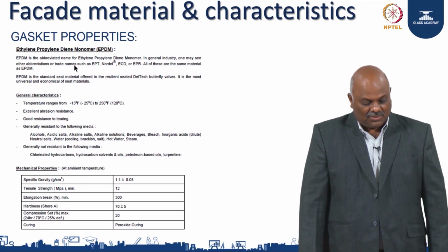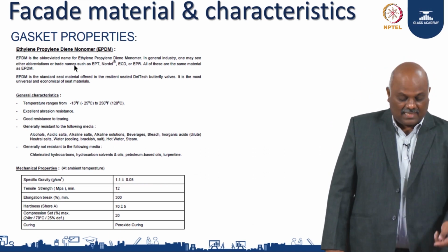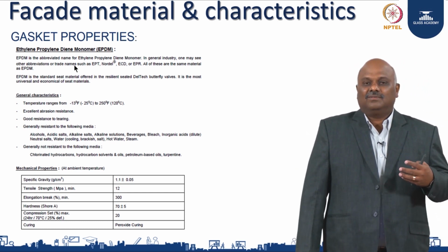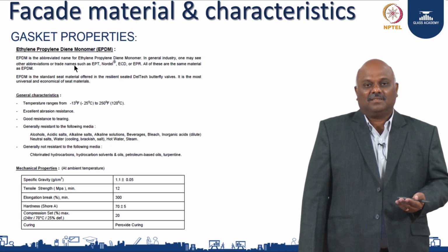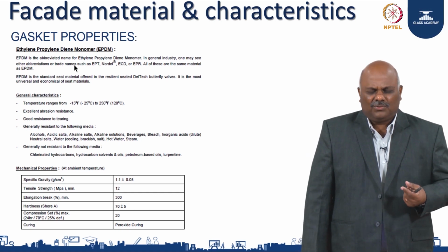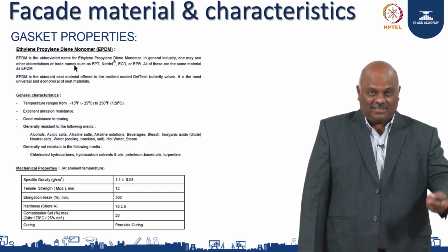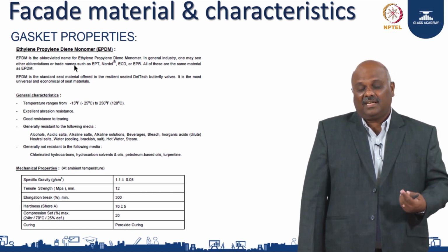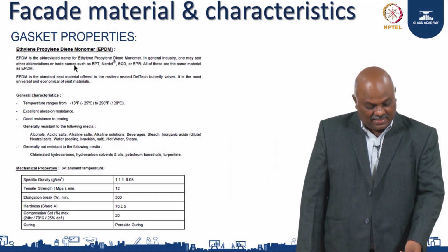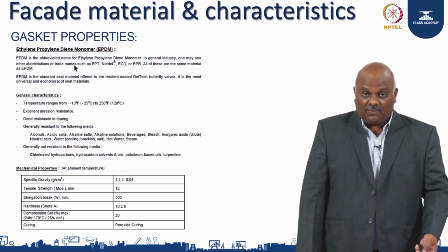So, these are the properties. If you run through, you will see EPDM, and again the choice of gasket and its hardness depends on your requirement. It is not something you just get off the shelf and put up. So, you design it, you understand what strength I need, whether it has to be too flexible or I want it harder. So, you increase the hardness of the rubber. When I say rubber, it is EPDM or silicone or whatever material you have. So, the choice of elasticity you choose. These are the factors. If you see here, elongation, how long you want to elongate, when you want that to break, what hardness you need.